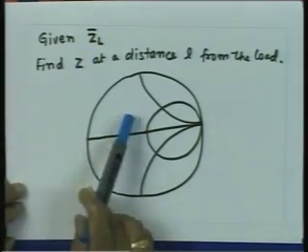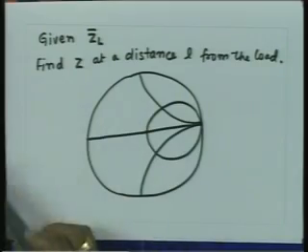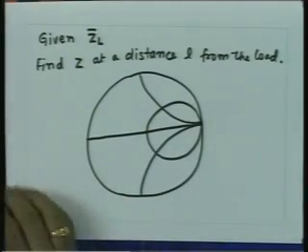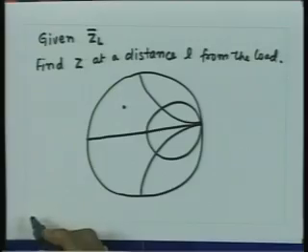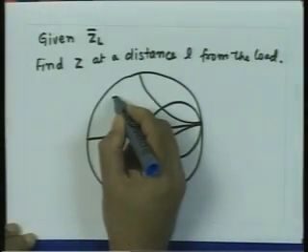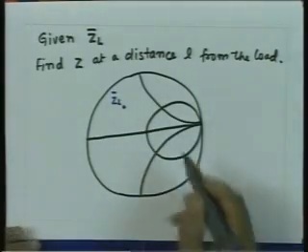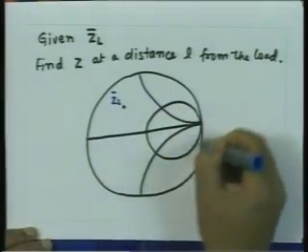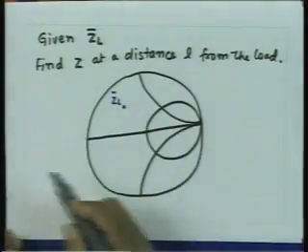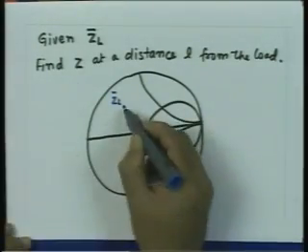Mark this impedance on the Smith chart as we did in the previous case. So, find out the constant resistance and constant reactance circles corresponding to this load. The intersection point of these 2 circles will represent the load, which is ZL prime. So, this point is ZL prime. So, that corresponds to this circle passing through this, a circle which is a reactance circle passing through that. So, this is my load point.